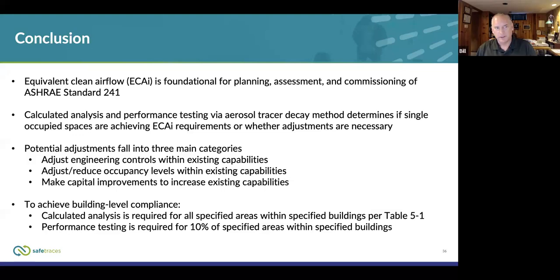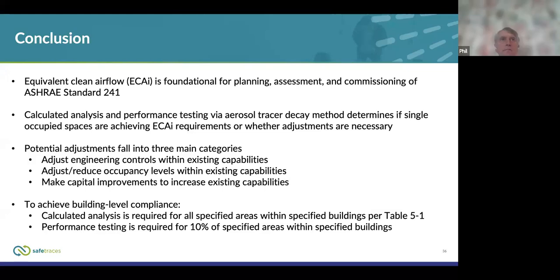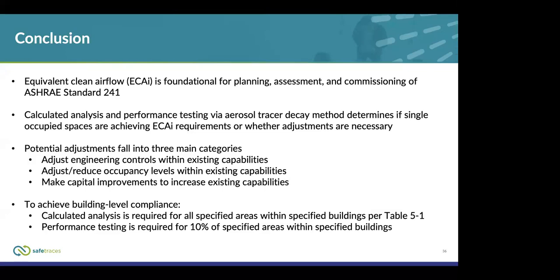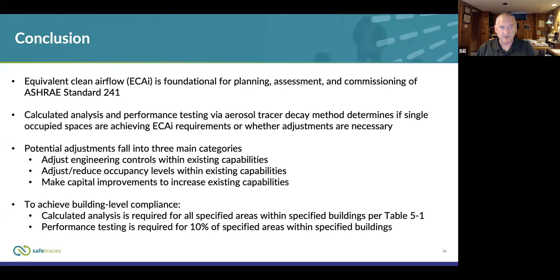You need to look at normative appendix A, which is all about testing air cleaners. It fills in chamber test requirements for any type of air cleaner that works in the space, which could be an ionizer, it could be upper room UV. It also addresses duct mounted air cleaners that work in the space. So if you put a PCO device in a duct and that puts reactive species into a space, that's covered.